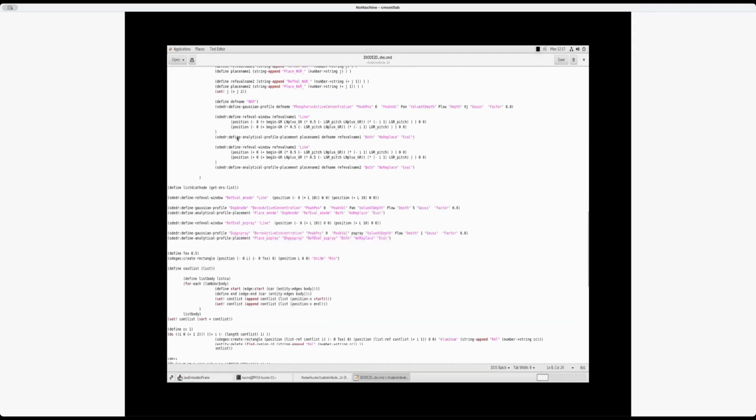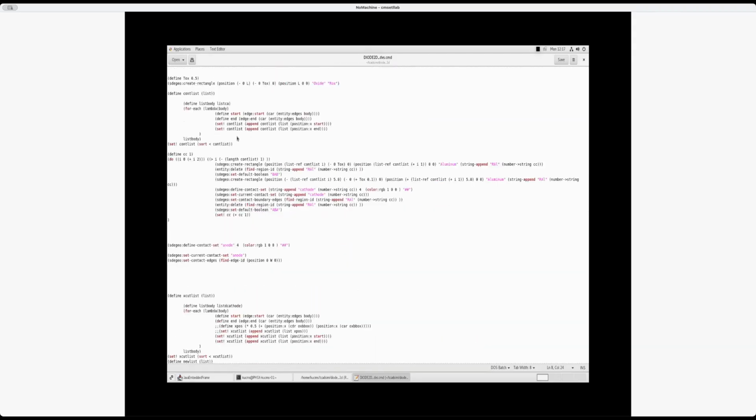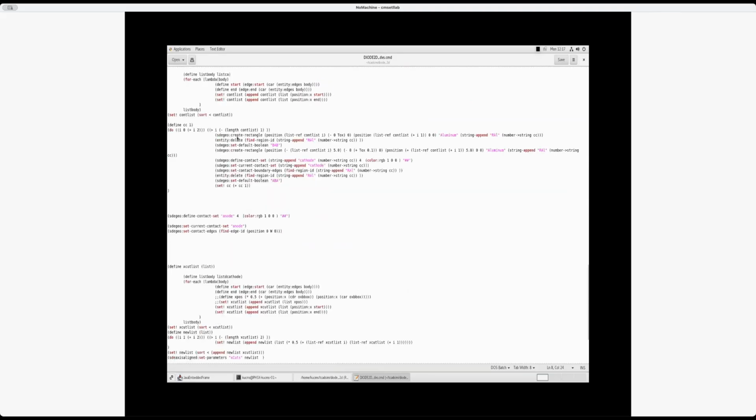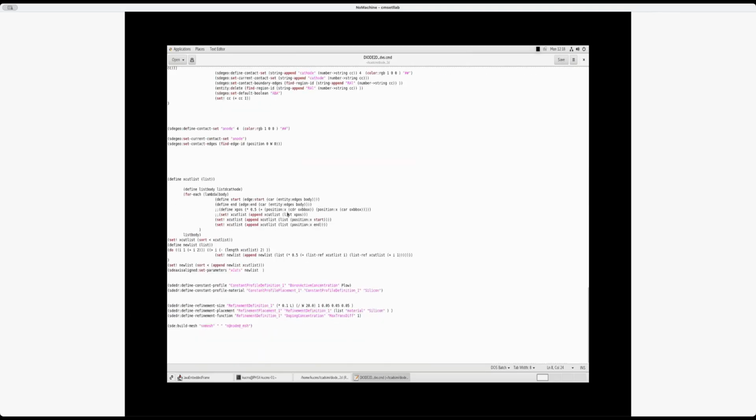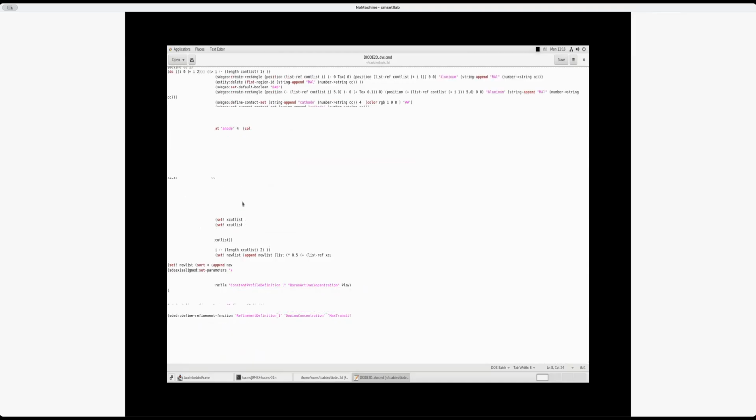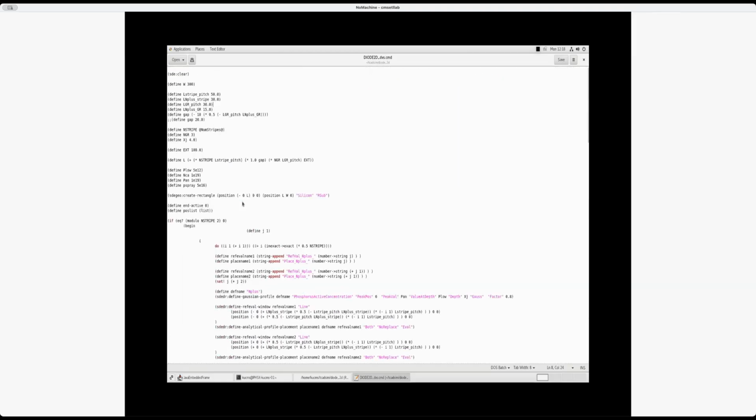I won't go into detail right now because it's explained more in detail in the slides. But you have essentially a scripting language that exists for the device editor that allows you to script the building of a device, from the geometry to the doping profile to the contacts, depositing metal like copper and aluminum, defining them as electrical contacts and such, and outputting all that at the end to the tool.